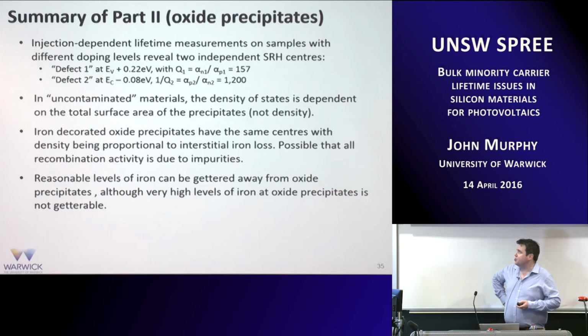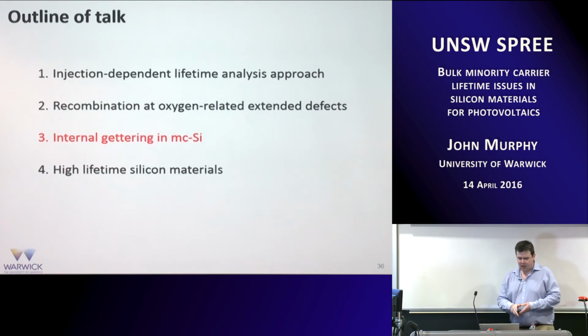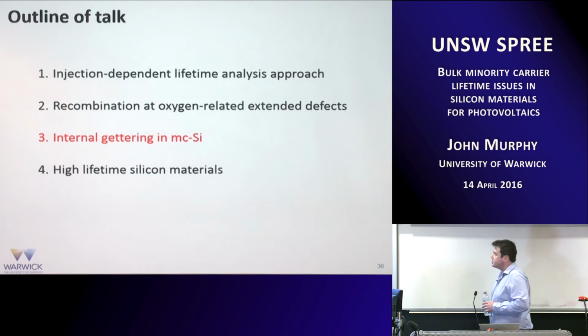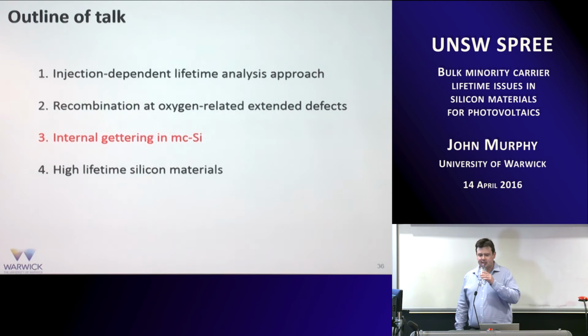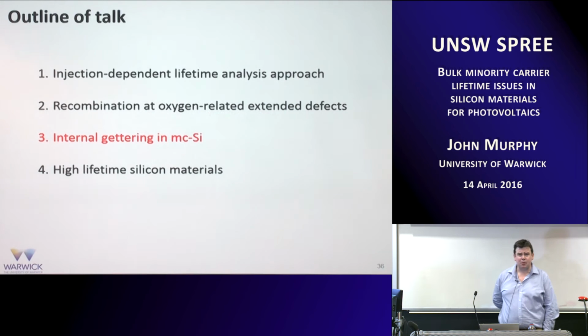In the third part of the talk, which is essentially the final part of the talk, I'm going to talk about something totally different, which is not using injection-dependent lifetime measurements per se. It's about internal gettering in multicrystalline silicon. So it's on a similar theme. It's about lifetime, bulk lifetime, but we're moving from high lifetime materials into low lifetime materials.